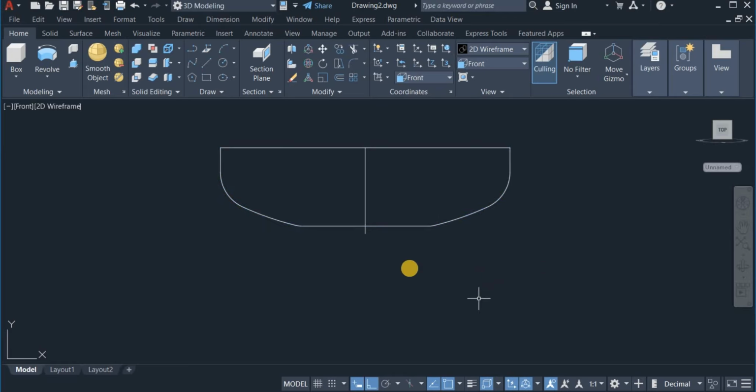Okay. So I'll now use the offset command to offset this polyline inwards by 3 units. So click on offset command, enter 3 units, which is the thickness of the dish, then offset this inwards and execute this command. Okay.